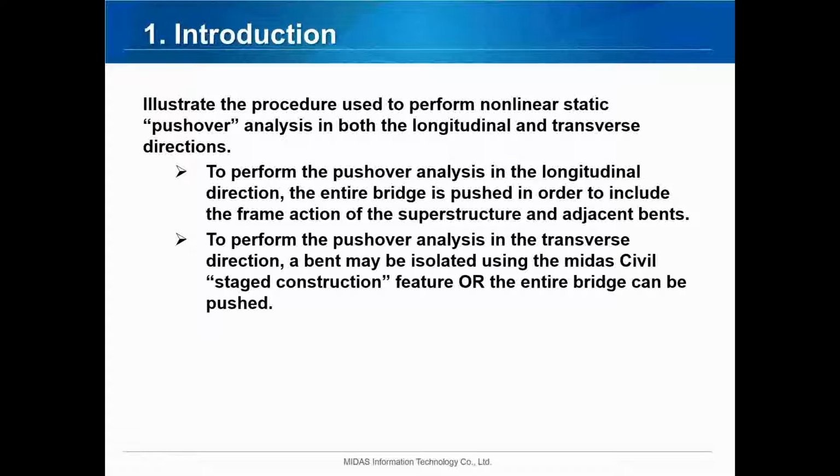We'll go over nonlinear material properties and plastic hinge properties for members, and a little bit of demonstration of that using MIDAS Civil. We'll talk about the capacity spectrum method and how we use that to efficiently evaluate our nonlinear seismic response and performance. And we'll go over the model setup, displacement demand analysis, displacement capacity analysis, and lastly, we'll briefly look at the AASHTO code requirements.